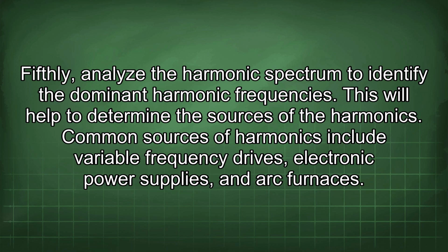Fifthly, analyze the harmonic spectrum to identify the dominant harmonic frequencies. This will help to determine the sources of the harmonics. Common sources of harmonics include variable frequency drives, electronic power supplies, and arc furnaces.